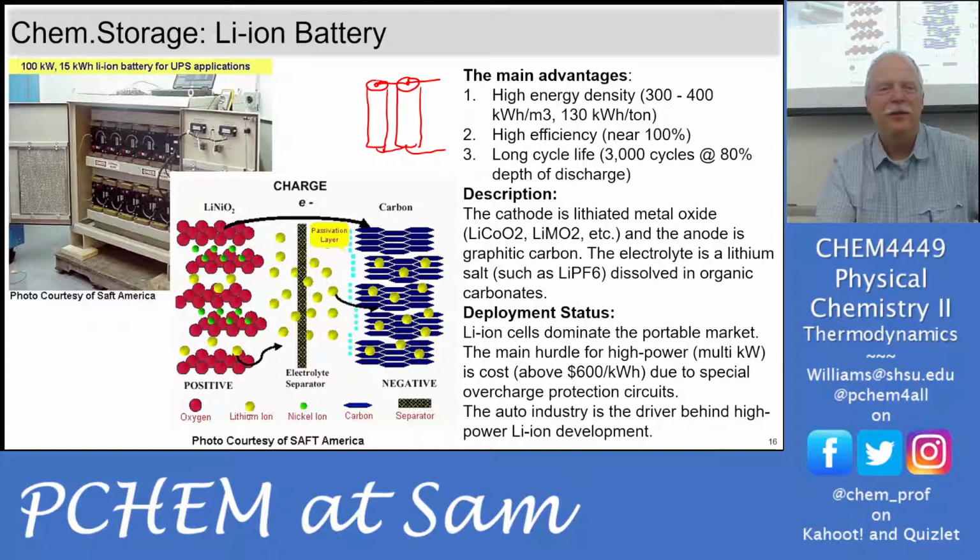So he got on YouTube and started looking up how to do this. And you can make a spot welder with a car battery. You just need to buy one automotive solenoid, and you need something that will pulse that solenoid for a programmable amount of time, like just 100 milliseconds. He has a Raspberry Pi that can send that signal to the solenoid. And so he made a little spot welder. You've got a couple of copper wires, hooked straight into a car battery, and a little solenoid that's computer programmable.